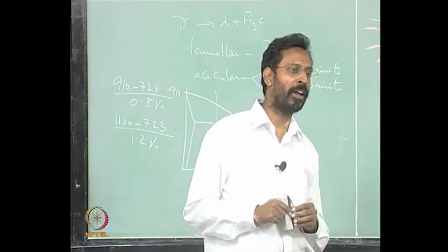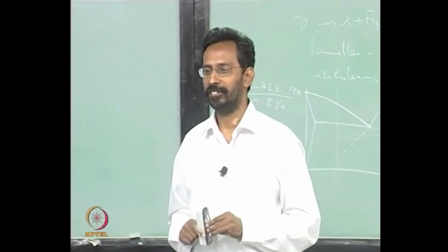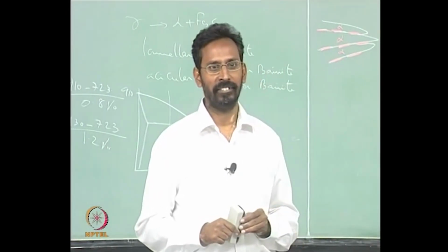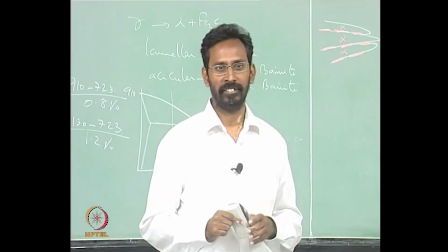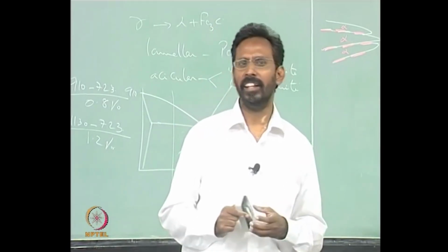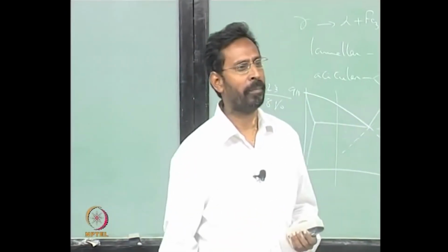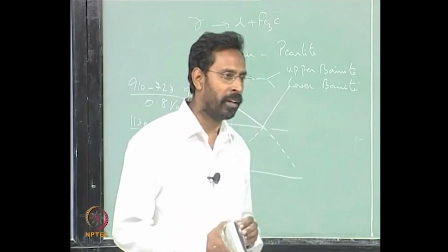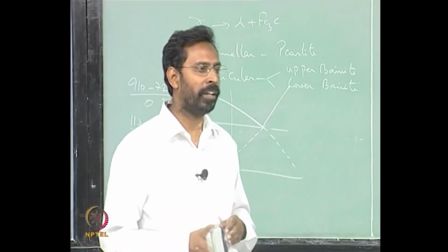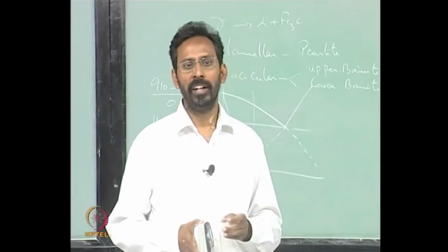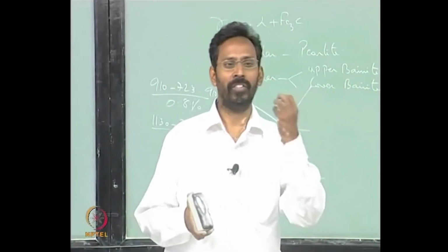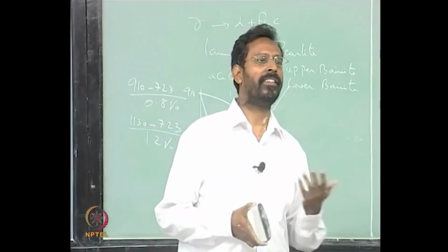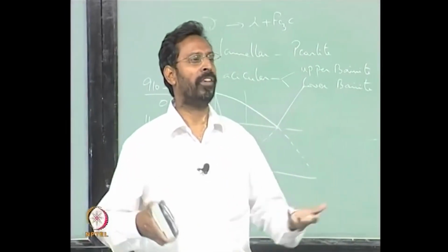Why is hardenability higher if the carbon is higher? Again diffusion problem, whenever you have a high carbon steel, there is more stress inside. If you take an austenite with 1.5% carbon and an austenite with 0.4% carbon, if you are comparing these two, you would see that because a large amount of interstitials are occupied by these carbon atoms, the diffusion is more difficult. Each carbon atom would be an obstacle for another carbon atom to move.